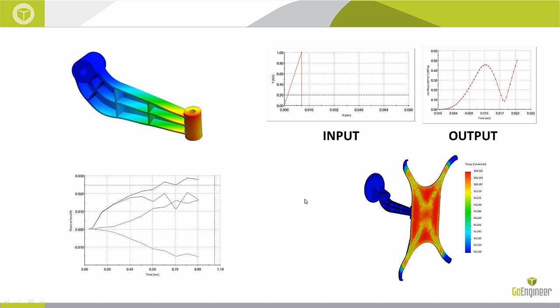Here I walked through a simple static structural analysis. I threw this into a vibration environment. I threw this into a thermal environment to figure out the final shape of the component in case it's hot. And finally, I looked at what kind of force the customer needs to apply in order to assemble this component together.